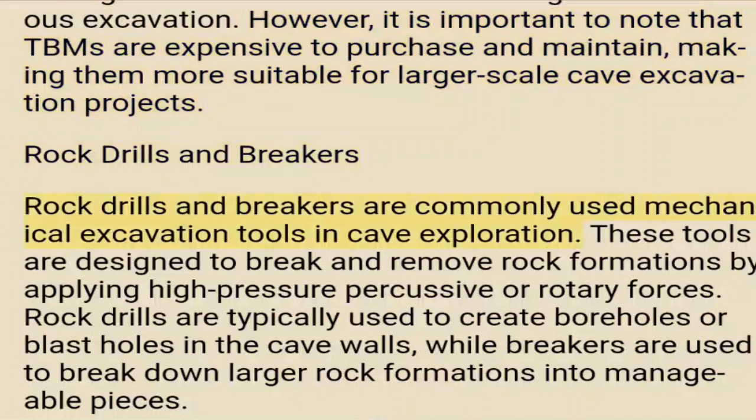Rock drills and breakers are commonly used mechanical excavation tools in cave exploration. These tools are designed to break and remove rock formations by applying high-pressure percussive or rotary forces. Rock drills are typically used to create boreholes or blast holes in the cave walls, while breakers are used to break down larger rock formations into manageable pieces.